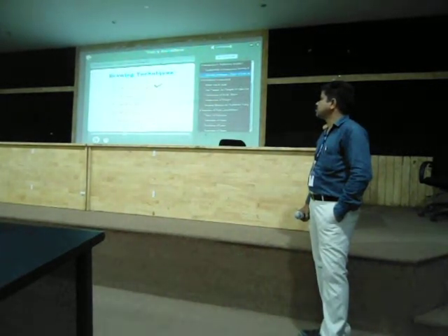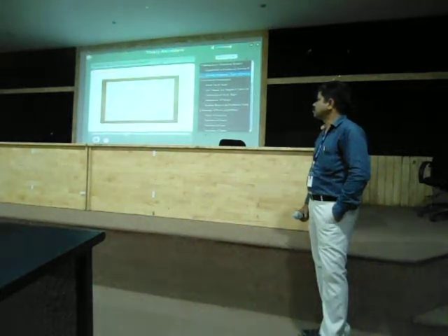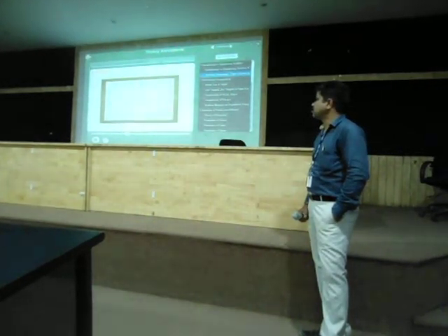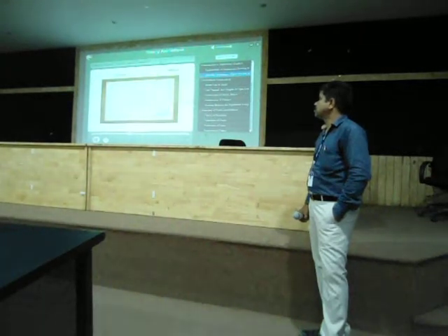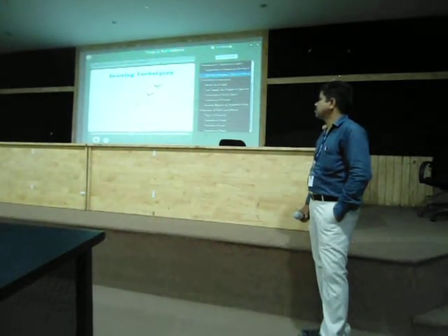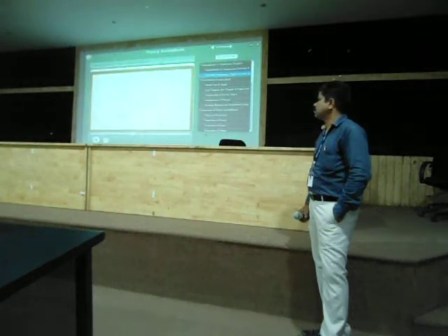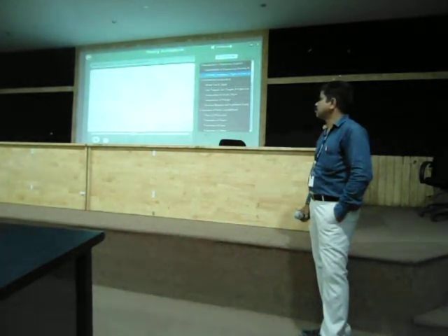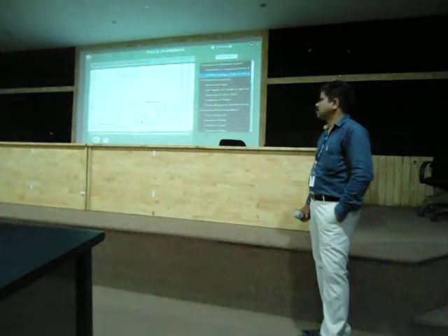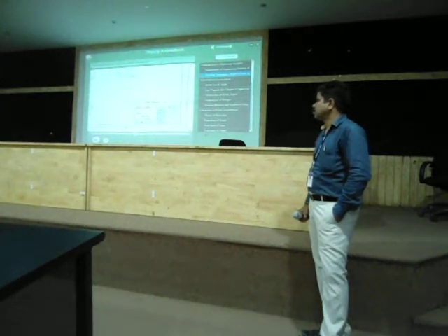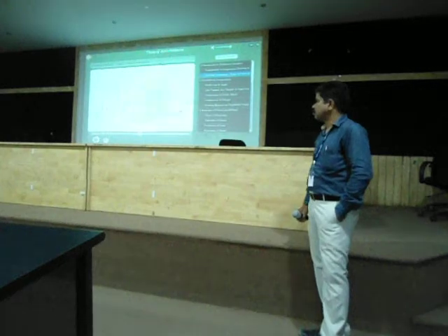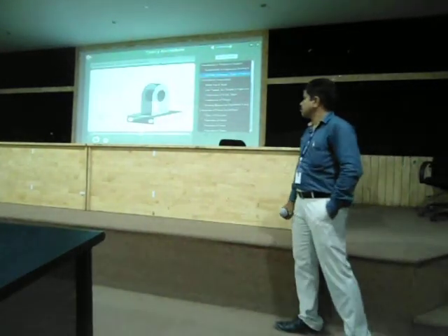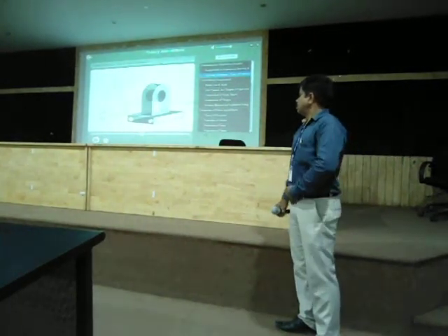So, we are all set to move on to preparing our drawing paper. We have to put together layout on paper, including margin, border, and other entities. The engineering drawings may also contain letters used for dimensioning, writing instructions, notes, titles, labels, etc. The term used for engineering drawing text is lettering. Next element is line. Lines are the predominant and the fundamental drawing element in every drawing.